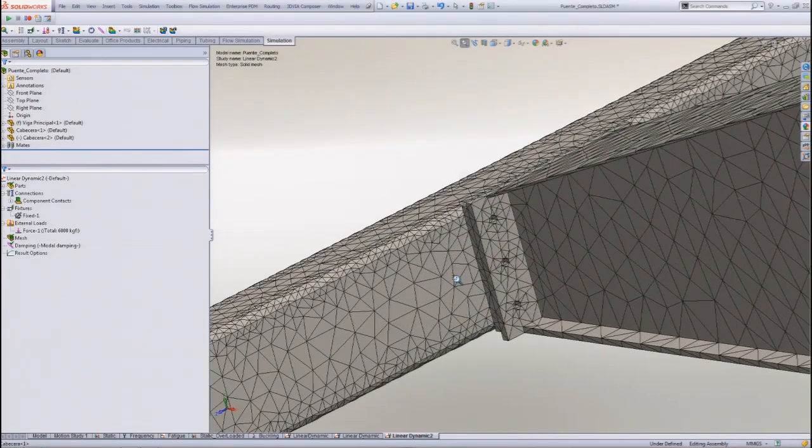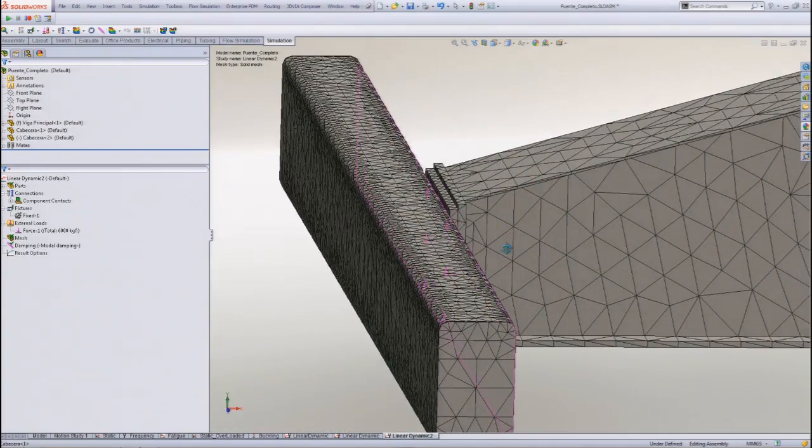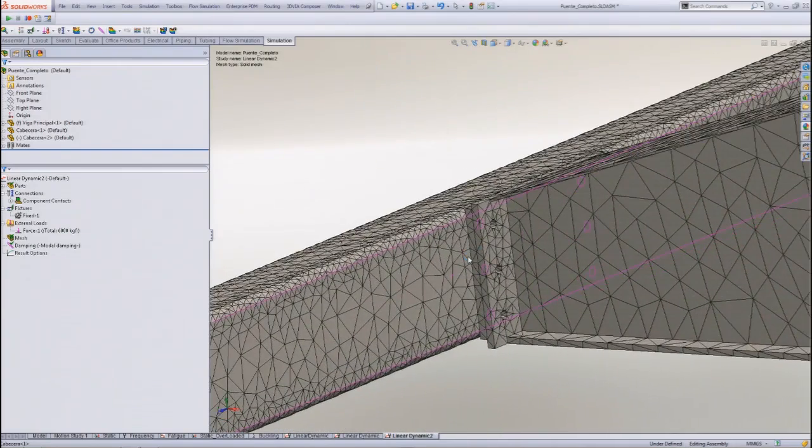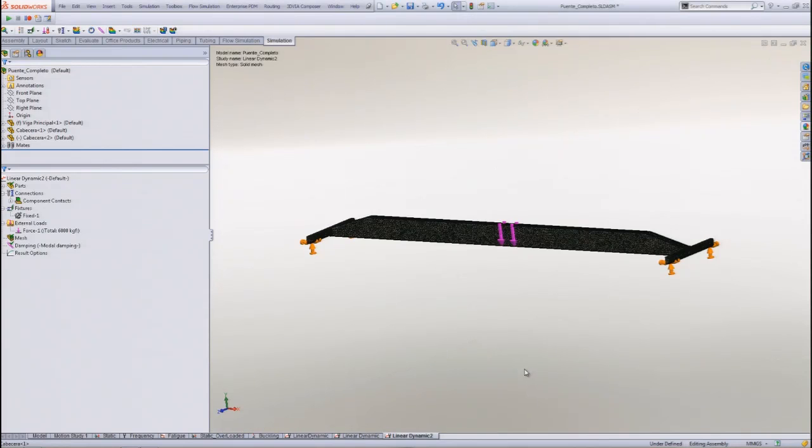You can see we use a solid model. Also, maybe another option here is to use a shell element. It's okay, but we wanted to use solid because we wanted to go further with the joints, and we want to run some fatigue on those bolts and joints. And after that, you have to run the simulation. So as a summary, you have to put fixtures, damping, load, with the load-time curve. That's it.